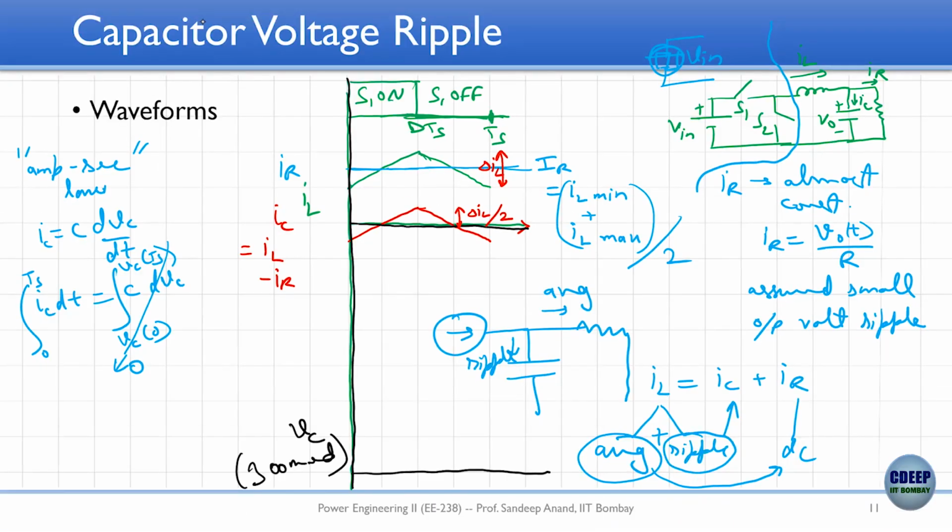And keep that in mind, I equal to C dV by dt. So you have I, you have to draw V, that's it. So if I use I equal to, if I write this way, from this full thing is Ts period, right, so this middle point will be dTs period. So if the full period is Ts, half of it is dTs, right, I'm focusing on the capacitor current, the red waveform. The point at which this current is crossing here is equal to dTs by 2.